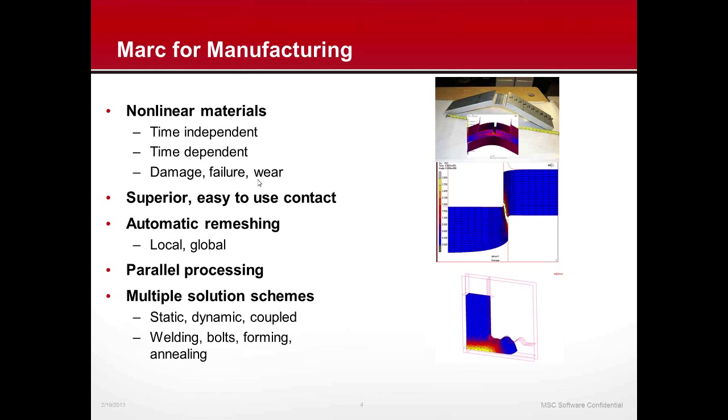That needs to be understood so that you know when the tools themselves need to be replaced so that the rejection rate of your products is not high. And with Marc, you can compute the progression of wear based on Archard's equation, which is defined as a function of temperature, normal stress, and the relative velocity between the two bodies that are in contact.